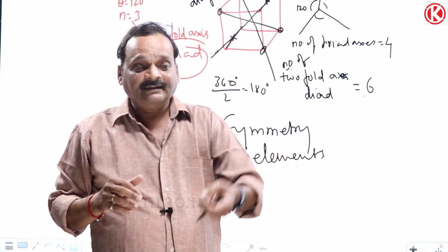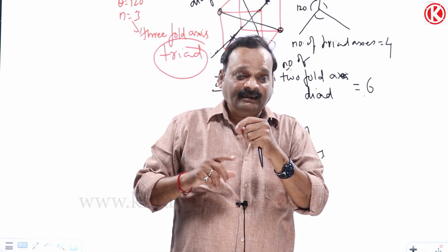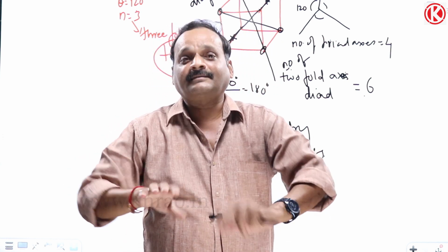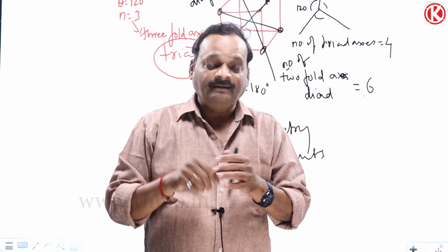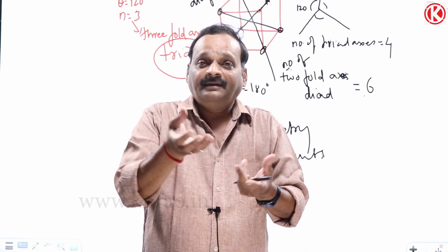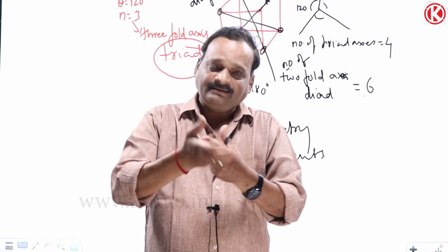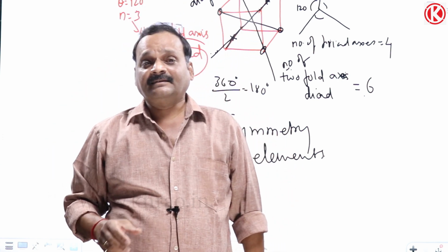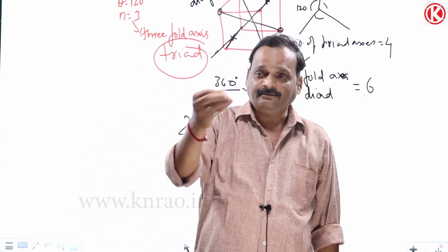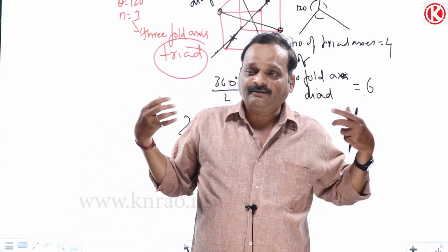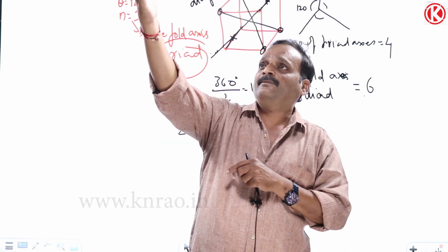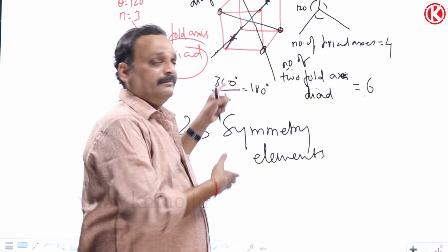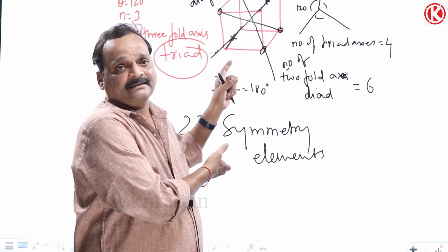Next one, if there is some more special property, like the electric dipole moment can be reversed in a pyroelectric effect, it becomes a ferroelectric crystal. It becomes a ferroelectric crystal where we use something like barium titanate or PZT crystals, etc., which are used in small sized high capacity capacitors. Those things will be clear once I go into dielectric material. But this is our foundation actually. There will say simply crystals which are not having center of inversion are piezoelectric in nature. We don't discuss all these things here because we have already discussed them in our cubic systems. Okay, right?